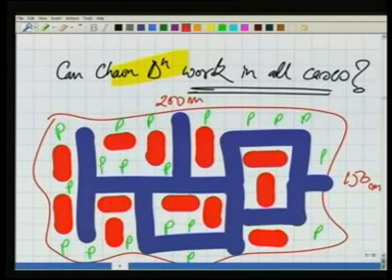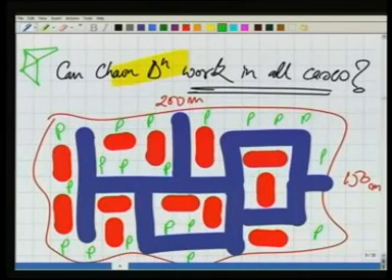Well, what kind of triangulation can we do here? Can we think of some triangulation scheme? The important thing is, in the case of triangulation, all the 3 stations should be intervisible. This station, this station, this station, all these 3 should be intervisible.